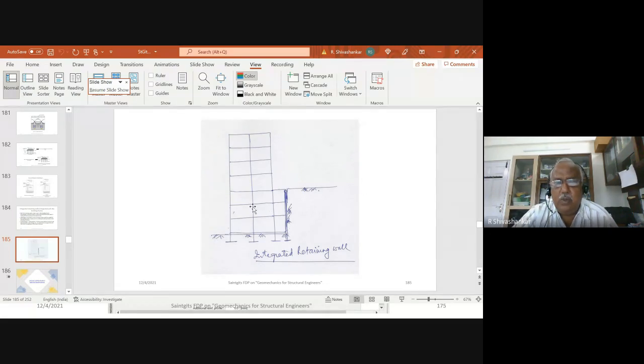So then what you can do is you can build this structure and then extend these beams at the different floors. You can have a column, so you can have a grid of beams and columns here very close to the cut or touching the cut, and there can be a slab between those beams and columns, a two-way slab.